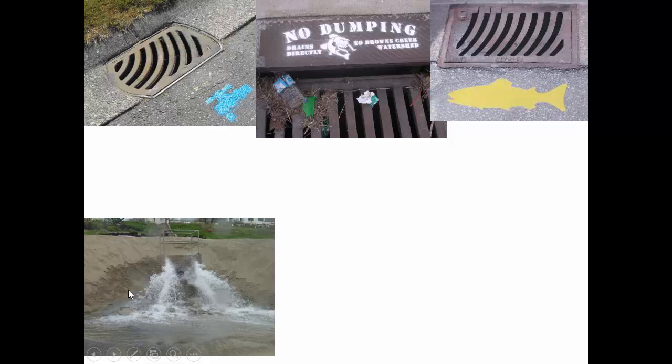This is a photo of water that's coming out of a stormwater network and into a flow equalization pond. And the purpose of that pond is twofold. Number one, it's to reduce the peak flow rate that's getting into a stream, because if all of the pipes conveying water from roadways carry water to the stream when there's this burst of rainfall, if it all gets there very quickly, it can erode the stream and cause a lot of damage. And so it's good, number one, to reduce the peak flow, so you're kind of evening out the quantity that gets into the stream at any given time.